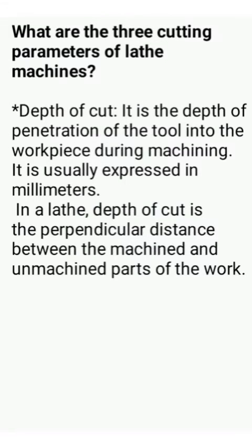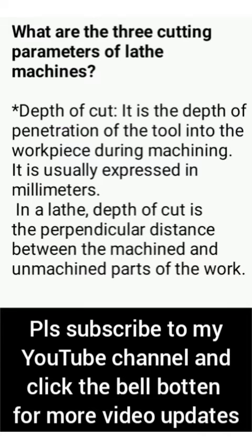Still on the parameters, we have the depth of cut. That is the last. It is the depth of penetration of the tool into the workpiece during machining. It is usually expressed in millimeters. In a lathe, depth of cut is the perpendicular distance between the machined and unmachined part of the work.